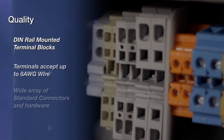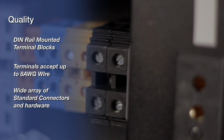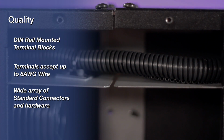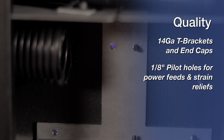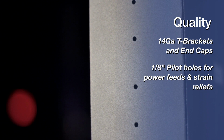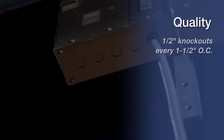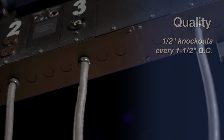All circuits are fed by DIN rail mounted terminal blocks that accept up to 8-gauge wire, as well as a wide array of available connector types and hanging hardware. All T-brackets and end caps are 14-gauge steel, with 1/8-inch pilot holes for side power feeds and strain relief connections. Half-inch knockouts are located every 1.5 inches on center throughout the length of the device.